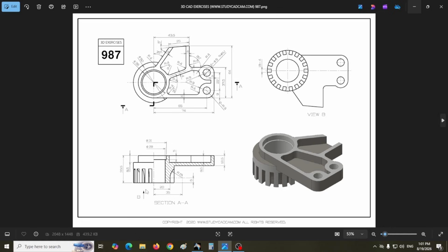The first parts I draw are the gear cylinder and the cylinder above it. In the second step, I draw the rectangular block. In the next step, I draw the part that is connected to the rectangular block. I will place the rectangular block in another body. I will show you the reason when I use the shell tool.